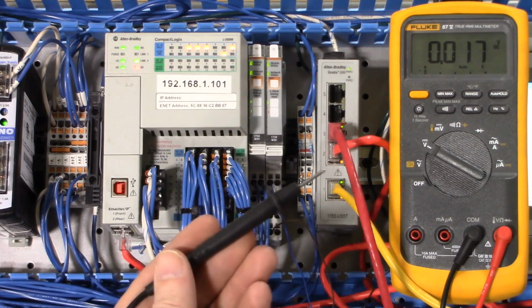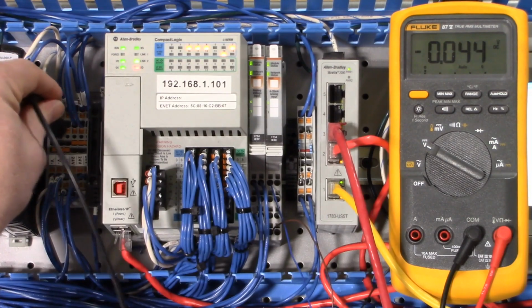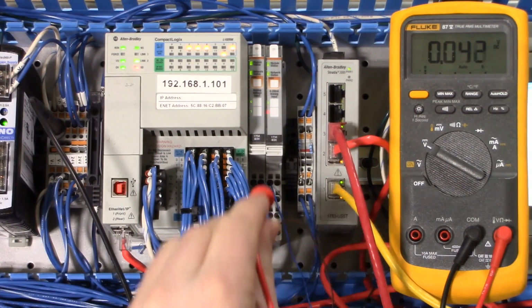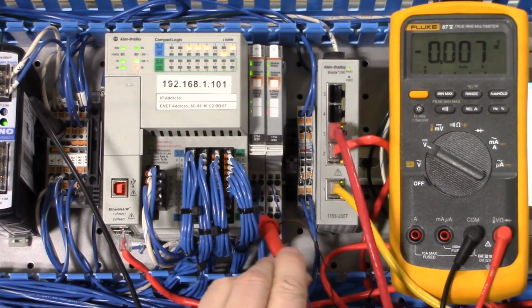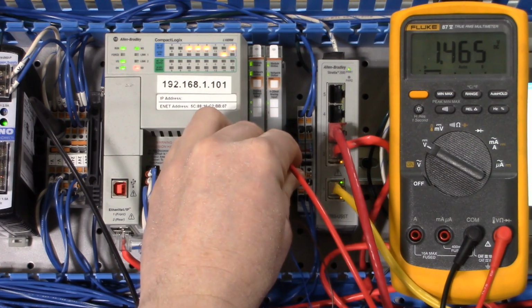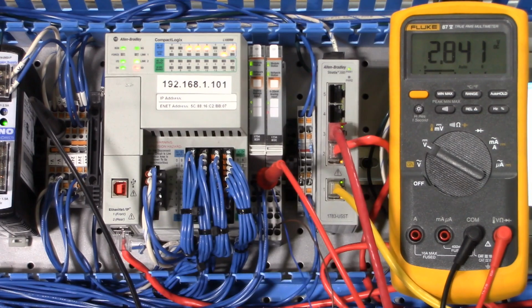So if I grab one lead and place that on a voltage negative, and then bring the other one to a test point, I've got to find out where that channel connects, and I'm not sure I can actually get my meter in there. Yes, I can. Okay, I was able to gain access and touch the wires that are going into that channel from the potentiometer. As I rotate the knob, on potentiometers labeled 0 to 100, not visible on the screen, as I rotate this upwards, I get numbers from 10.33 volts all the way down to 0 volts. It's variable based on the location of that potentiometer. I should be getting that for both of the voltage inputs going into this module.